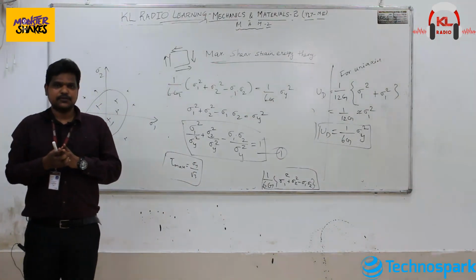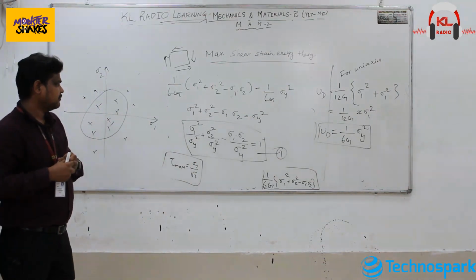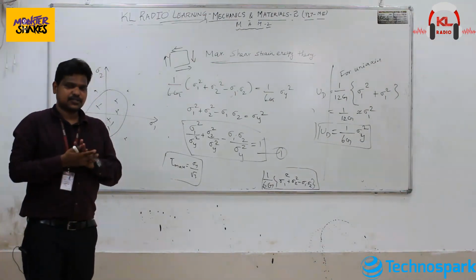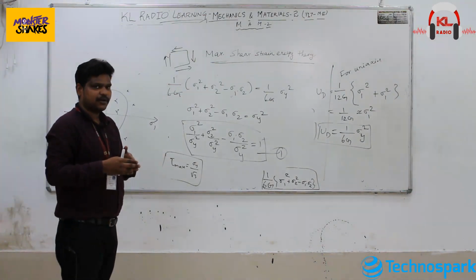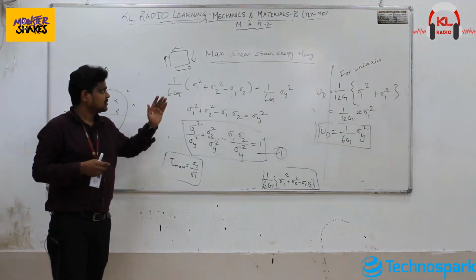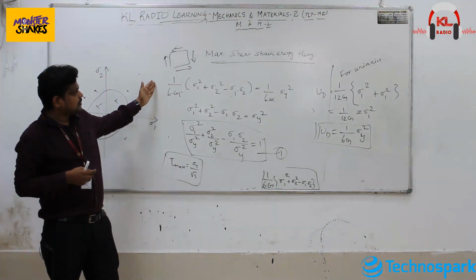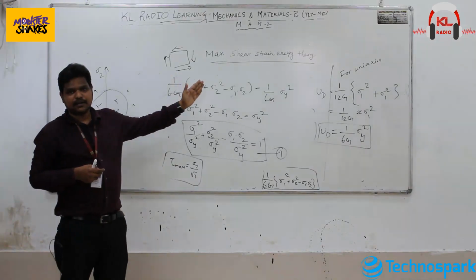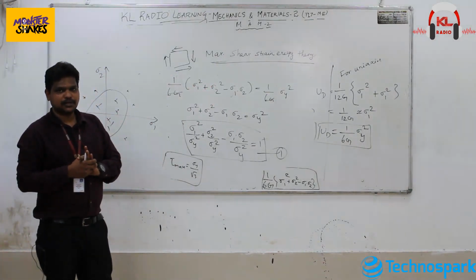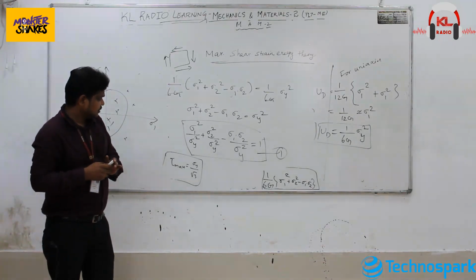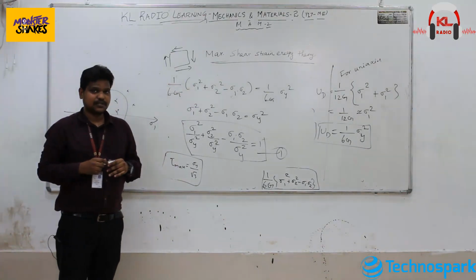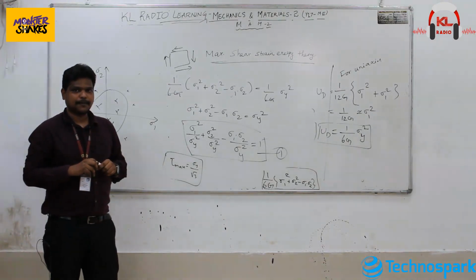But sometimes you may use maximum shear stress theory for a material which plastically deforms, or is ductile, or even a pure shear case. Even the maximum shear stress theory can be used, and von Mises stress theory can also be used, but von Mises stress theory will give a more accurate result. Due to this, we will choose the distortion energy as a failure criterion.